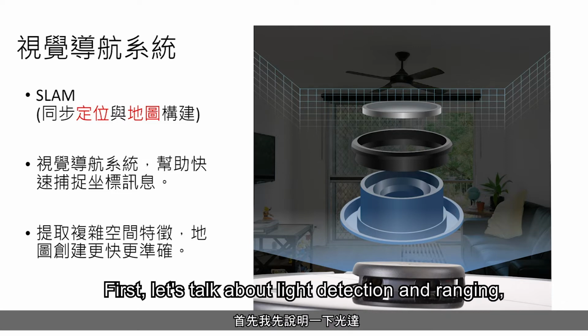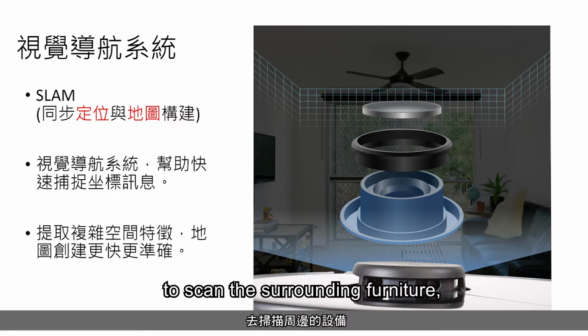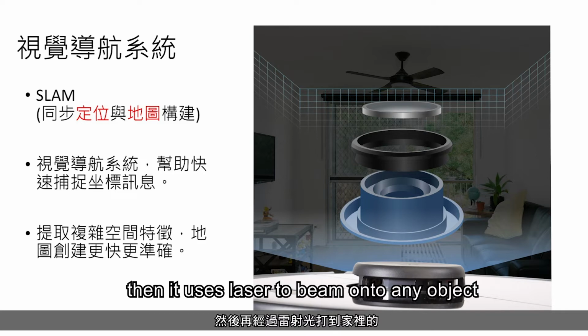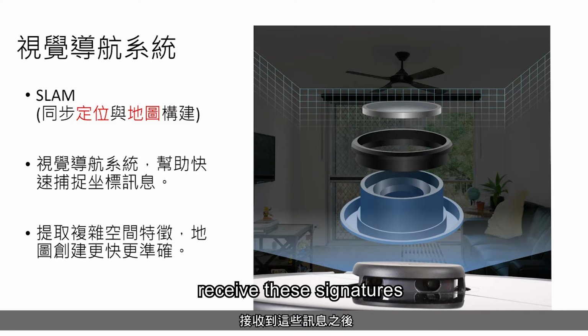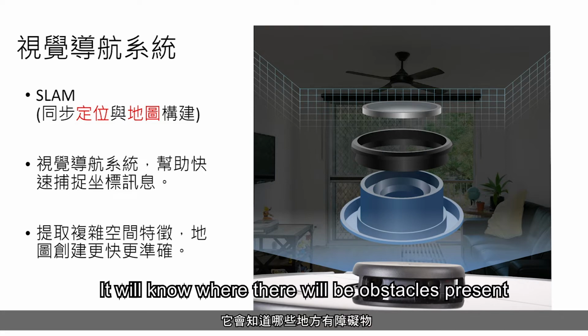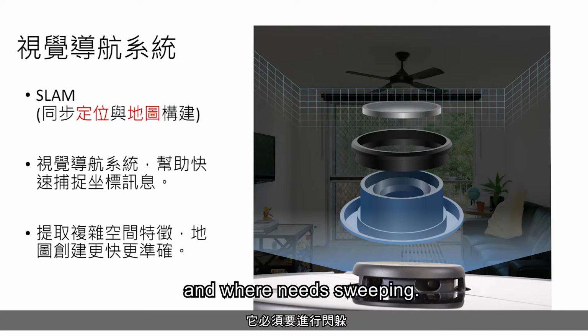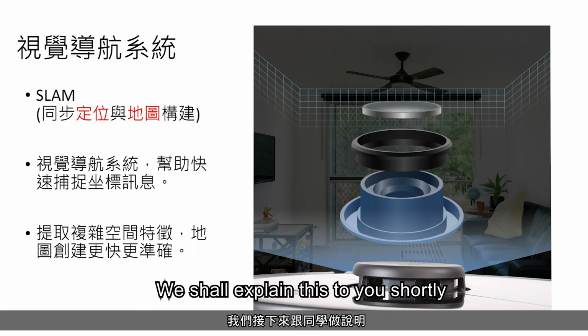First, let's talk about light detection and ranging. LiDAR uses laser beams to scan the surrounding furniture. Then it uses laser to beam onto any object within the household, which will reflect the light back, and our LiDAR system will receive these signatures and reconstruct a 3D model of the household. It will know where there will be obstacles present and where needs sweeping. The other type uses imaging. How is imaging achieved? We shall explain this to you shortly.